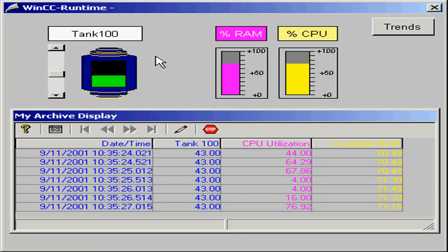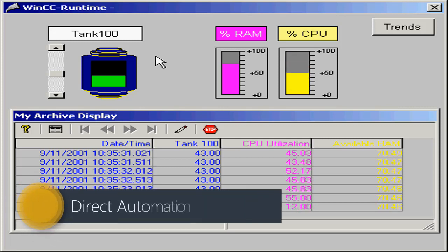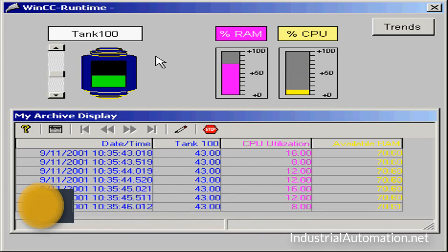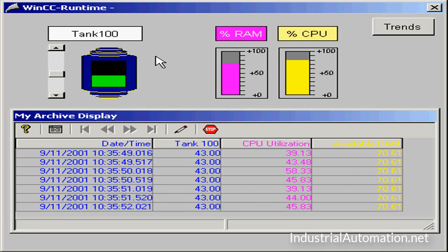Many industrial applications require that we periodically sample processed data and store it into an archive. Once archived, the data should be available for analysis, reporting, and viewing at an operator station. In this section, we'll show you how to configure this functionality using WinCC's tag logging editor. First, we'll look at an archive that's already been set up, then we'll review the steps necessary to build it.